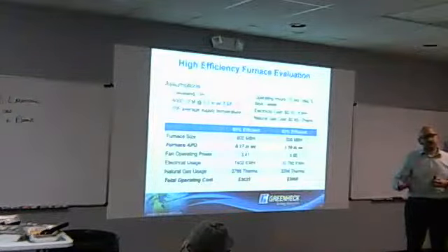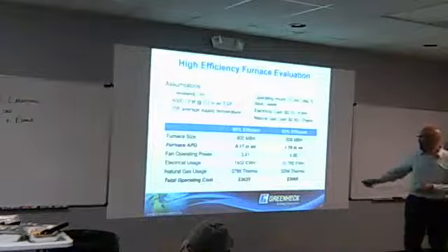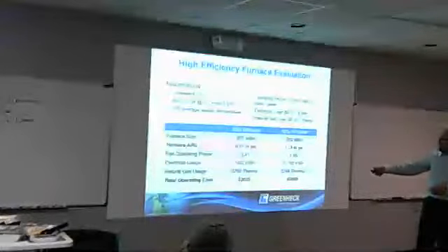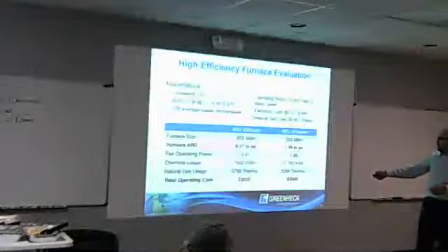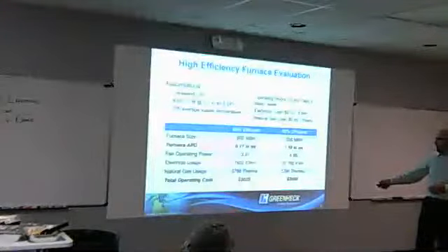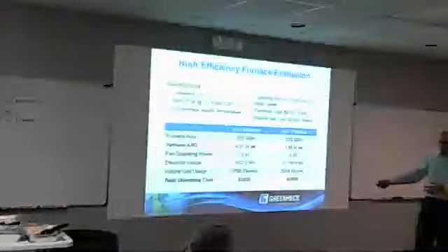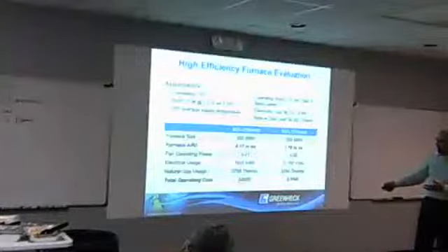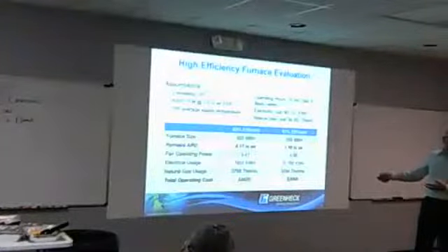One, the condensing flue gases, what are you going to do with those? Now you also pay for the pressure drop on the double heat exchanger and secondary heat exchanger. Your operating power is going to go up, electrical usage goes up, and a little less gas usage, but it's offset in a negative way by power consumption, and actually costs you a few more dollars to gain to 92%.